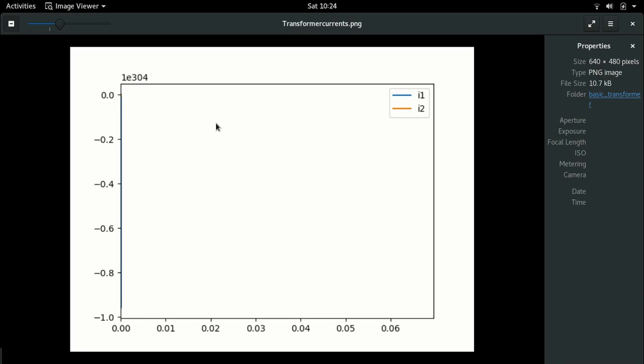So this is when integration time step becomes critical. Before, integration time step resulted in an error in the simulation. Now integration time step results in instability. A wrong integration time step results in an unstable simulation. So in this, I will stop this video now because it's already gotten pretty long. In the next video, I will talk about why this instability results and how we're going to solve it.